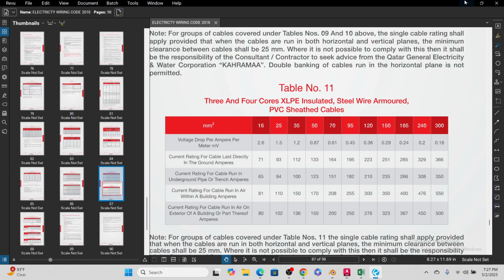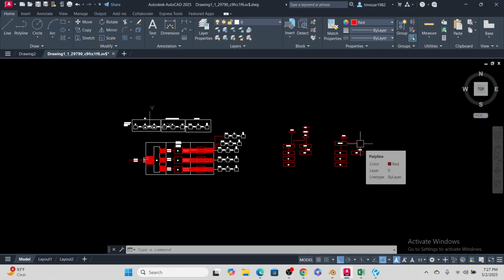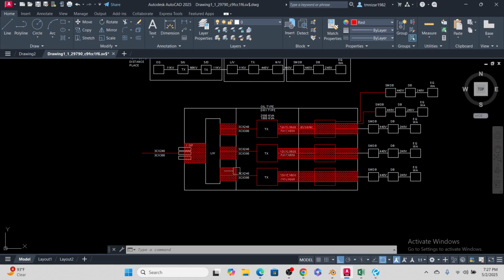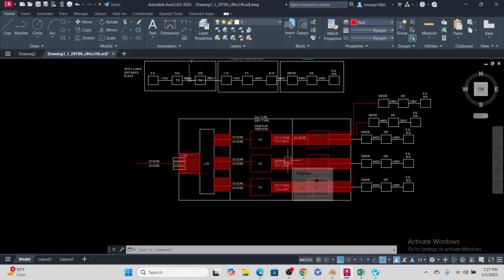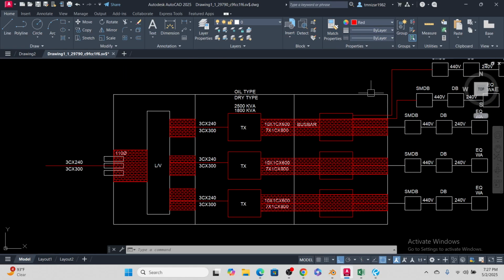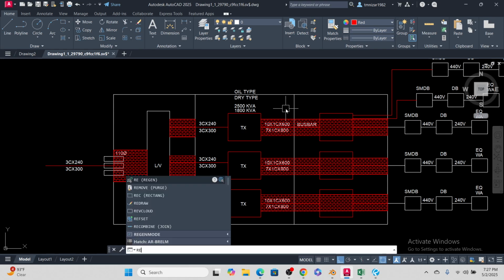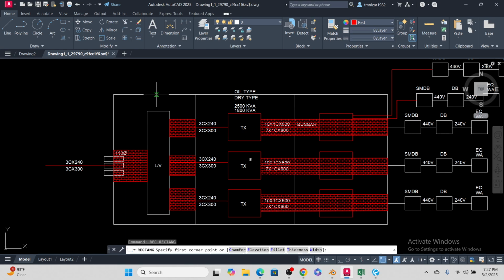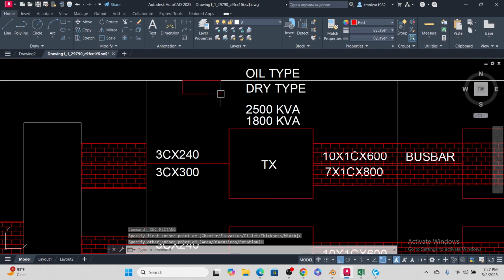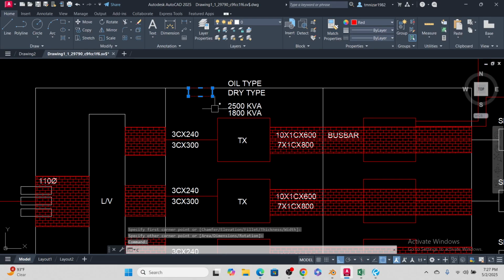So the next thing: inside the substation, this is feeding the power out to the building, everything. But inside the substation itself, we need some lights, we need some sockets, we need some emergency things, because in case something happens here, we need emergency supply also. So the same concept, there will be a DB here called DB TX, and there will be a DB here.